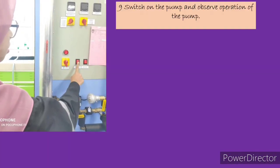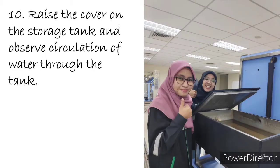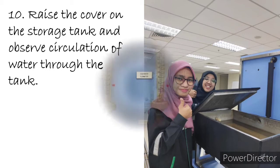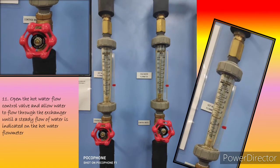Switch on the pump and then observe the operation of the pump. Number 10. Raise the cover on the storage tank and observe the circulation of water through the tank. Open the hot water flow control valve and allow water to flow through the exchanger until a steady flow of water is indicated on the hot water flow meter.